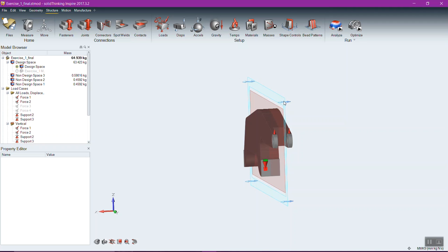And usually it's a multi-stage process where they push some of it in and then maybe bend something out and pierce a hole and push more. It's a very complex process, but the bottom line is it's a stamping process. And if you imagine taking a punch and pushing it down into a die, once that punch comes out, that part has to come out of the die, which means you can't have a part that's shaped like that. And you can't have a part that's shaped like that unless you turn it on its edge. But there are limits to what you can manufacture.